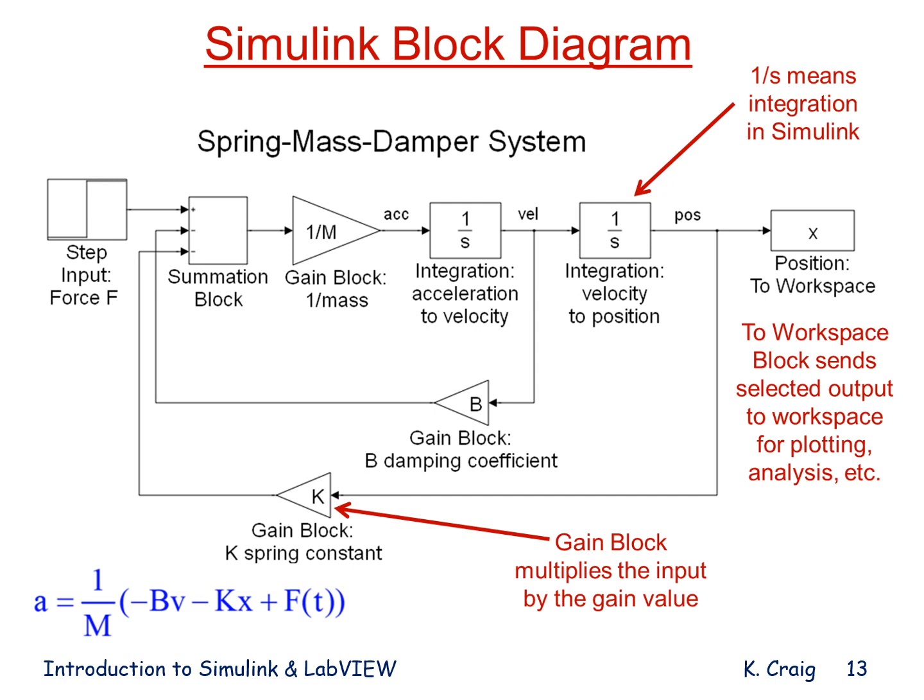Here is my Simulink block diagram, and this is for my mathematical model, which I show here at the bottom left corner. As you see, I have solved for acceleration, which in terms of derivatives is the highest derivative in my equation. Acceleration is the derivative of velocity. Velocity is the derivative of position. So this is the highest derivative in this equation.